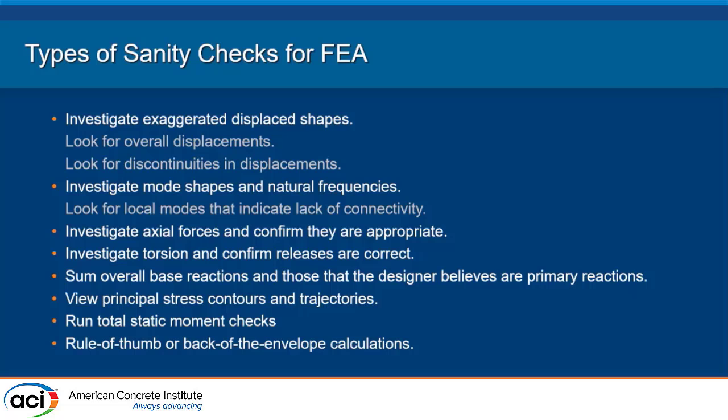Summing the overall base reactions for where you think the lateral forces are coming out in your model and making sure that you don't accidentally have restraints in your model that are dragging forces where you didn't want them. This happens on garages. Sometimes I see it a lot where the ramp acts as a shear wall if you're not careful, if you're not detailing it in the field and in your model consistently and correctly.